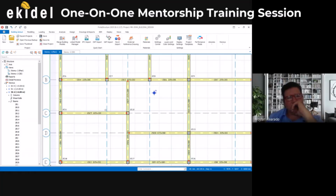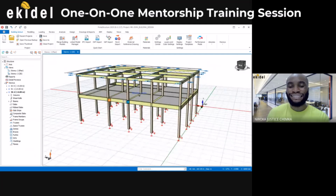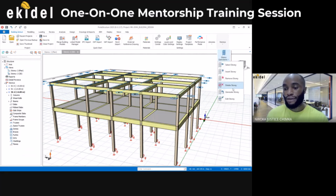Okay, so once you've done that, the next thing to do, if we come back to our 3D view now, is to insert the height, to choose the height of the ground floor and the first floor, because the height of the ground floor might be different from the height of the first floor. So now insert your height and all that, still under building set out here. Come to story here, which is the same place, story operation, and then you see edit story.